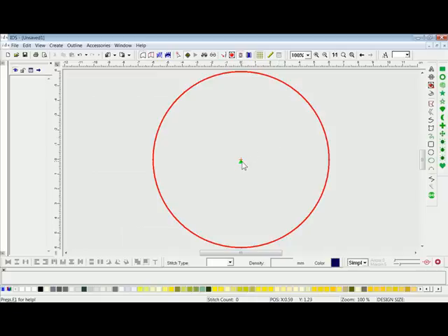We can also change the way that our grid is lining up on our design by going up to the upper left-hand corner where our two ruler bars meet. There is a gray box, and if we left-click, hold and drag on that gray box, bring that into screen, we can see we have two meeting lines. One is horizontal and one is vertical. If I'd like my grid to line up with that center point, I will place my cursor over that design center, let go of my left click, and my grid will shift to that point.